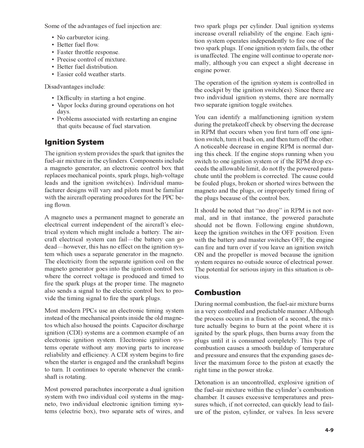Even with the battery and master switches off, the engine can fire and turn over if you leave an ignition switch on and the propeller is moved, because the ignition system requires no outside source of electrical power. The potential for serious injury in this situation is obvious.